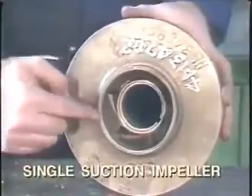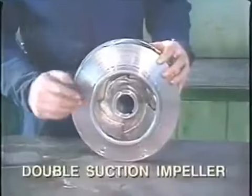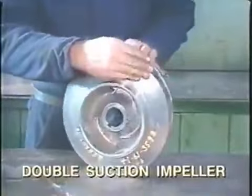In a single suction impeller, liquid enters the suction eye on only one side. For the double suction impeller, the liquid is allowed to enter on both sides. It's really like two single suction impellers placed back to back.